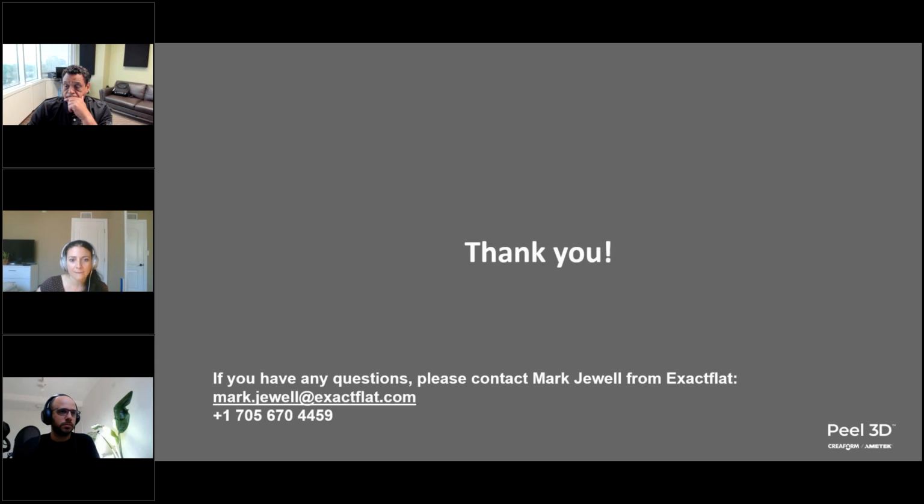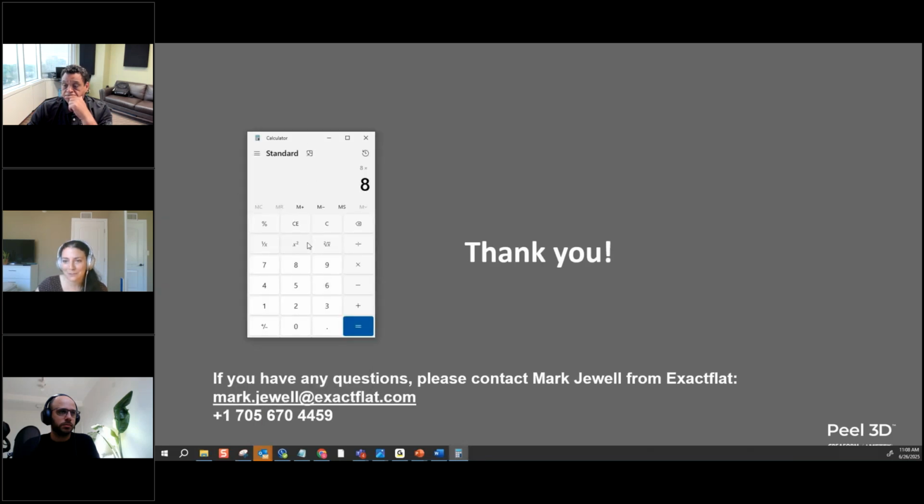So in the case of 8 feet, and I guess I'll do it over here on the screen so you guys can see it. If we're talking about inches, I'm going to be multiplying 8 feet times 1.2 thou, so that's going to be 0.0012. So that ends up being about 9 thou, maybe about 10 thou, but then there's also plus the 50, so it ends up being